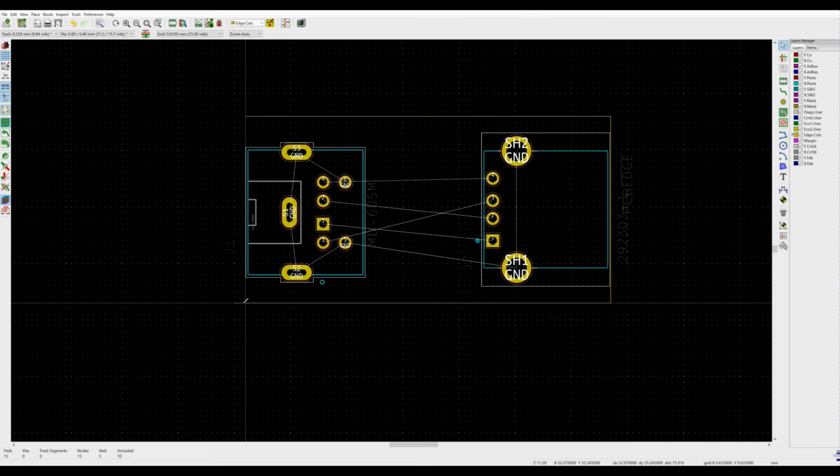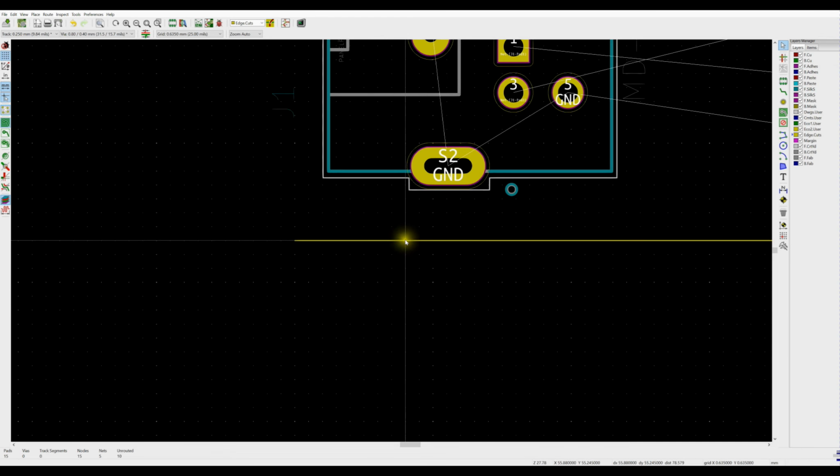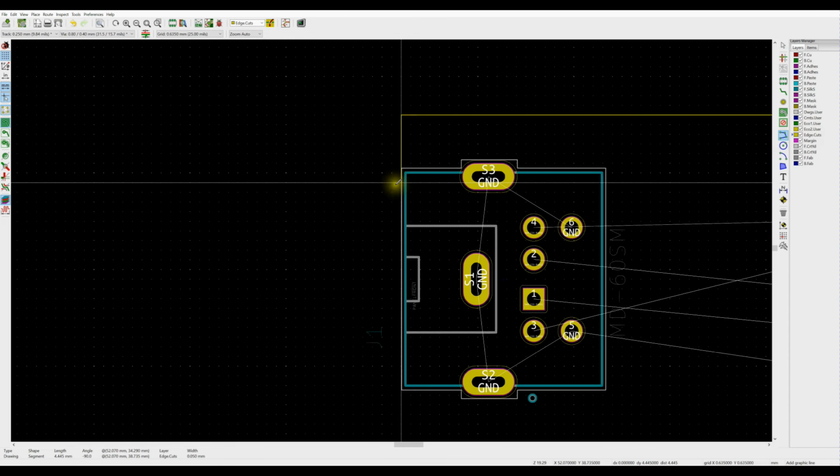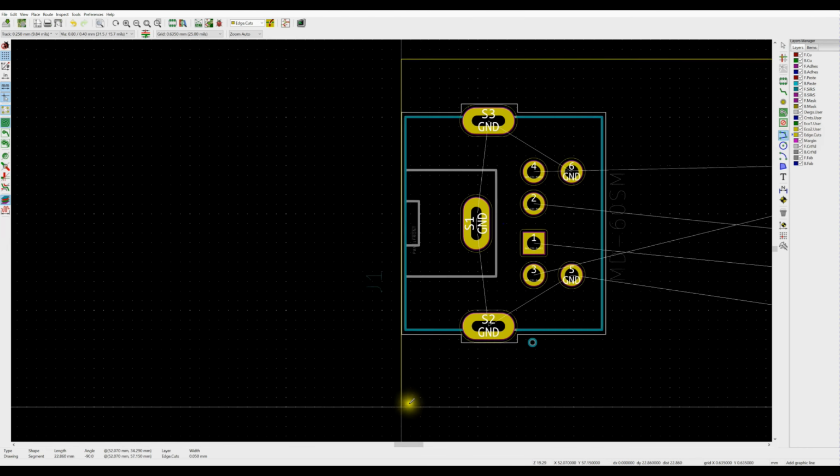And I did that wrong. Let's go ahead and delete that line out. Come back to edge cuts. Notice the little circle that pops up there. That says when I start drawing the line, it's going to actually connect to the previous line. These have to be continuous.